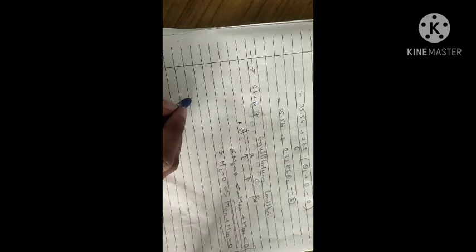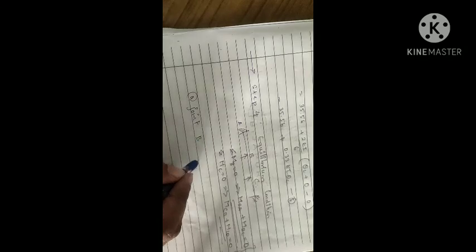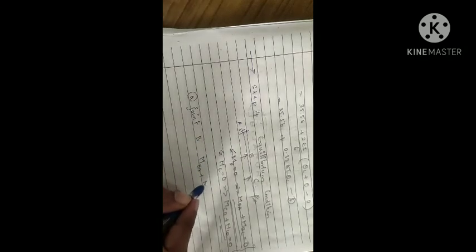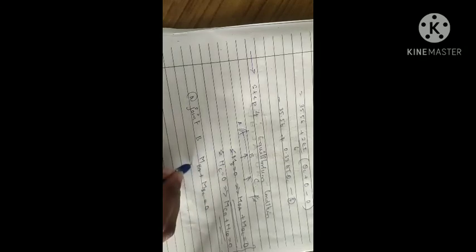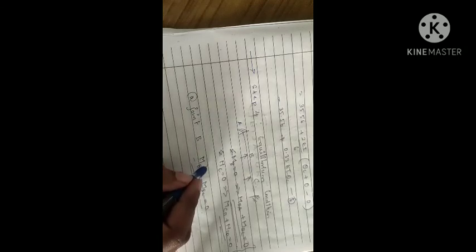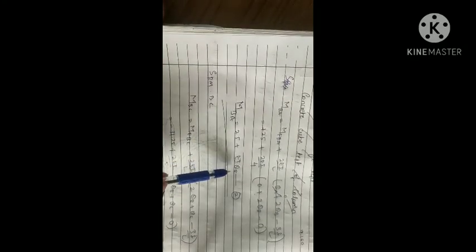So what are the equilibrium conditions? At joint B, MBA plus MBC is equal to 0. Now where can you find MBA? You can find MBA from equation 2 and MBC from equation 3. So for MBA, from equation 2, you write down what MBA is. MBA equation is 225 plus 2EI theta.